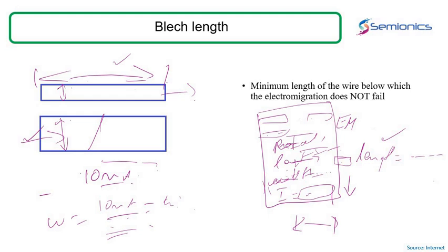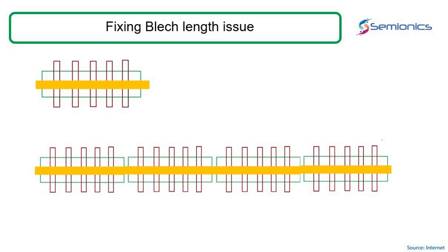So when you are dealing with high currents, it is very important that you pay attention to this factor as well. Say, for example, you've got a device over here, and you have calculated for, for example, 5 devices, based on the current equation, the width of the metal you have to use. Now there are 5 devices here. If you have arranged a row of devices like this, do you think this metal will be able to carry that much current?